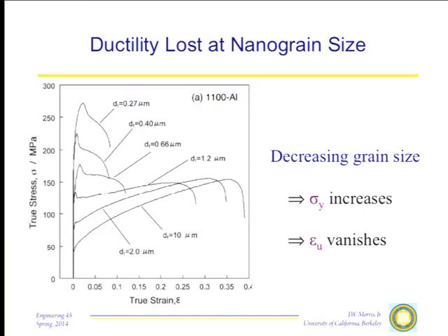You know, as an aside, it's simply a fact that when you actually make a device, there are all sorts of nooks and crannies in any device that you make, that the minute you turn that device on, there will be places where the yield strength is exceeded. Notches, corners, various such things. There's even a phenomenon called shakedown in machine design, where you operate the machine and you expect to see some transient deformations. The behavior of the machine will change slightly after you turn it on. And what's happening is that these places where, just because of geometric constraints, you're developing high stresses, in those places you're getting deformations, the machine is just relaxing itself so that the parts fit. And that's a natural phenomenon.